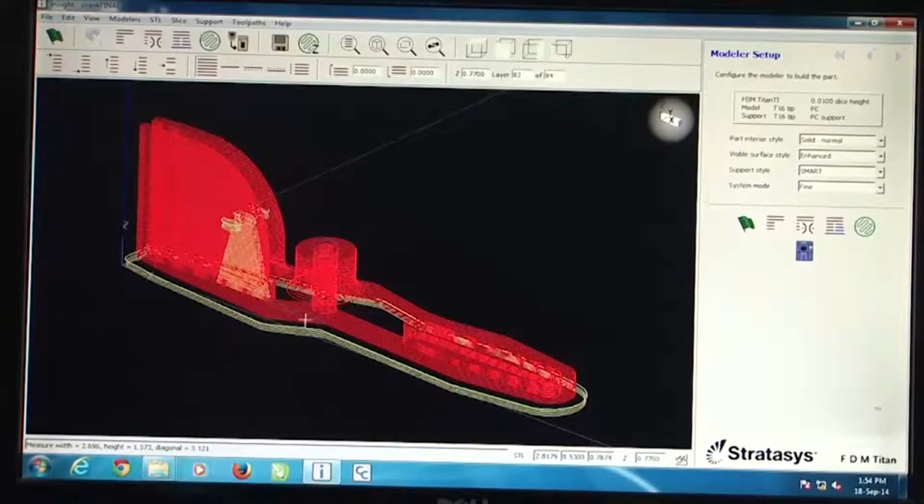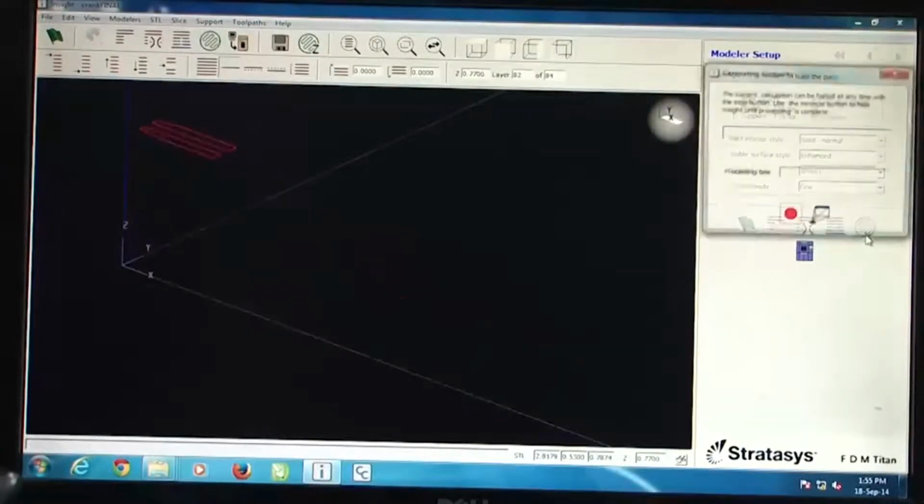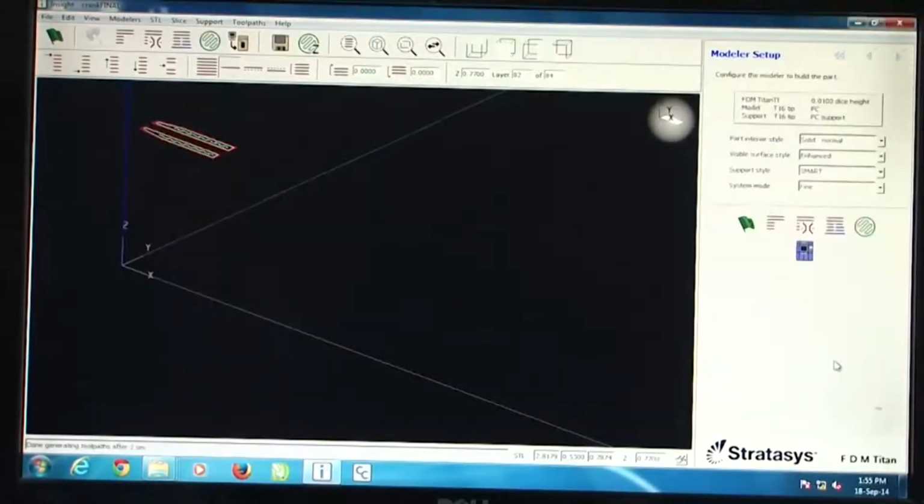So you have built up the supports here, and then finally we want to find out that within one such section, what is the tool path which is getting created. And the tool path is reflected by this green symbol, which is reflecting the zigzag motion of the tool path within such a domain. And I want to create the auto tool path. So the software now tries to compute and create a layer by layer tool path, so that you can easily look at, by going to the various layers, how the tool paths are varying.